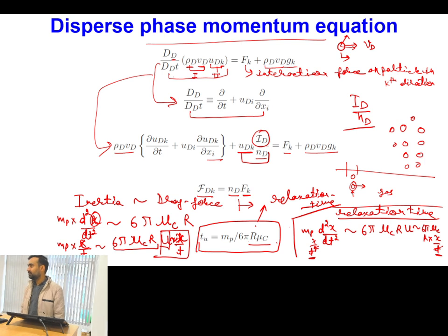Yes, in the derivation of the boundary layer, whenever we derive Prandtl's boundary layer equation. There we do order of magnitude analysis, and depending upon the order, if some terms are very small, then we neglect them.